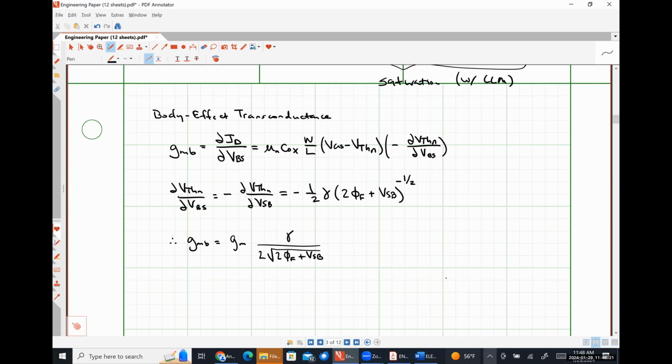So the internal capacitor in a MOSFET is usually incredibly small. Actually, there are four, but we're talking on the order of picofarads to femtofarads. So as long as we're not trying to amplify a signal in the megahertz to gigahertz range, those capacitors are effectively still going to look like open circuits to us.